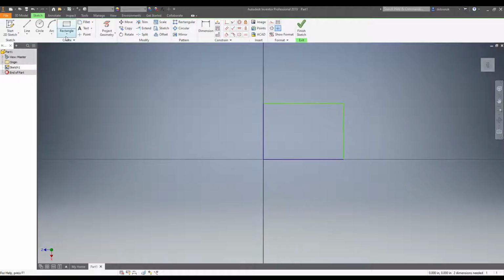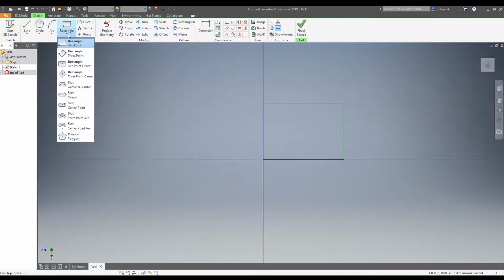So anytime we're selecting these pre-made sketch objects, it's already inserting quite a bit of the constraints that we need. So if those are the shapes that we need, it's a significant time saver. But keep in mind, if you're trying to work backwards by using a shape and then using that shape to maybe take away a side or two, then you're going to have to also delete those constraints because it could keep you from doing those things.